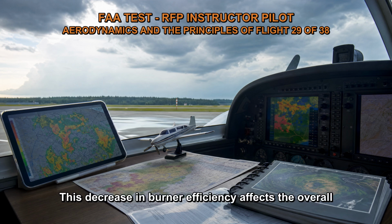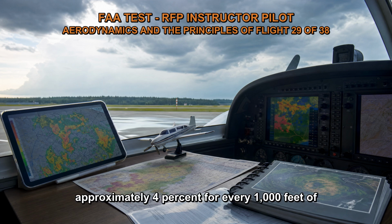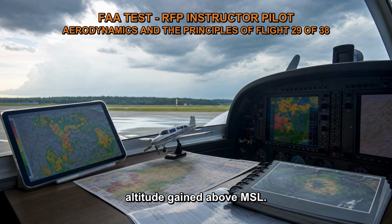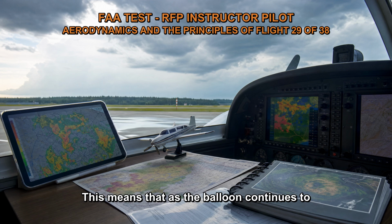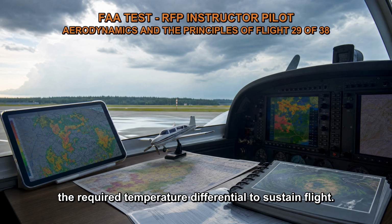This decrease in burner efficiency affects the overall heating of the air inside the envelope. The rate of decrease in burner efficiency is approximately 4% for every 1,000 feet of altitude gained above MSL. This means that as the balloon continues to climb, the burner becomes less effective at maintaining the required temperature differential to sustain flight.